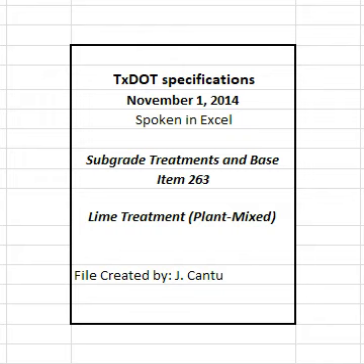4.3.2 Density control. Compact the bottom course to at least 95% of the maximum density determined in accordance with TxDOT 121E, unless otherwise shown on the plans. Compact subsequent courses treated under this item to at least 98% of the maximum density determined in accordance with TxDOT 121E, unless otherwise shown on the plans.